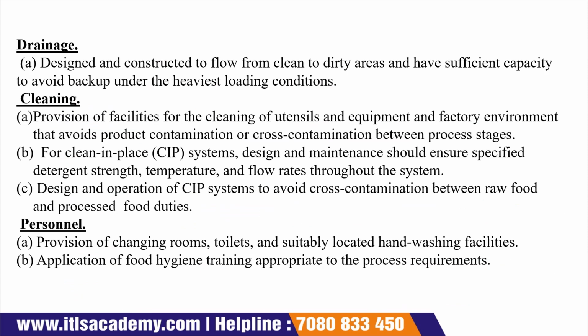Now the next is your drainage. Drainage is designed and constructed according to the flow which is produced inside the premises, so that it carries dirty water away, cleans properly, and has sufficient capacity to avoid backup under the heaviest loading condition. See, designed and constructed to flow from clean to dirty areas and have sufficient capacity to avoid backup under the heaviest loading condition.